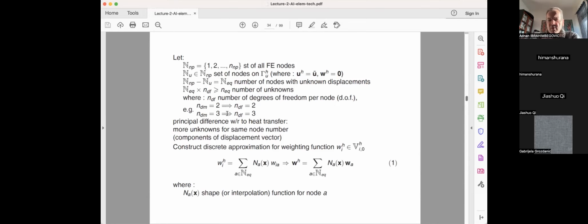Typically, you sweep the finite element mesh and see what the constraints are. You put those equations on the side, at the end, and all the active equations, that means the unknown displacements, you put up front, and this is the part you compute. Once you have computed the active part, then you go to the reaction part, and this is the way it works.